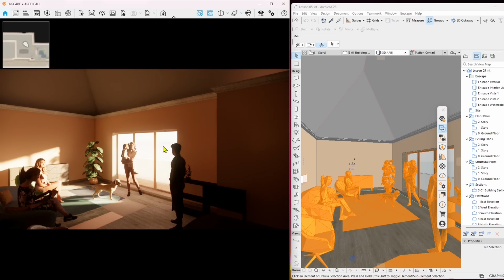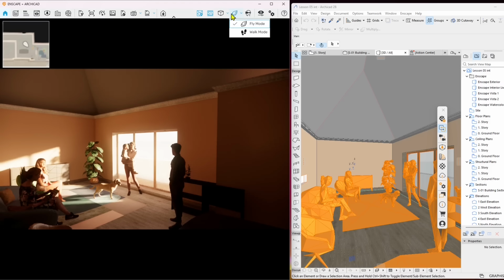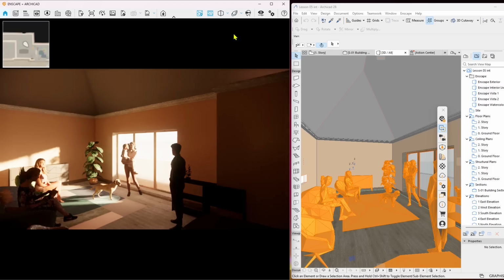So if you want to change that, we're gonna go back to the visual settings that we saw before. Up here, the little eye icon on the toolbar, all the way to the right, and also we have here the perspective. We already changed that, and my suggestion is to use the 2 points perspective because it's going to make straight vertical lines, and that's better when you work in architecture in general. So I would set here the 2 points, and I will keep that.